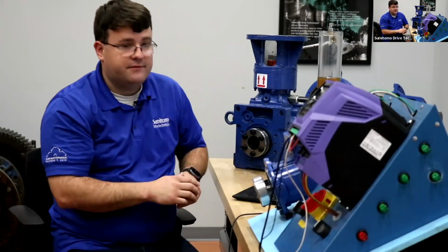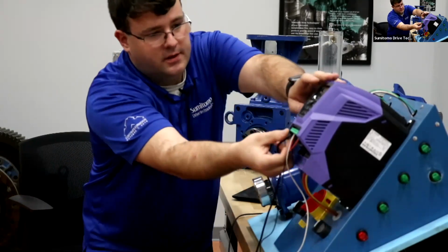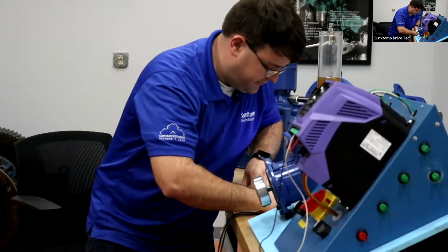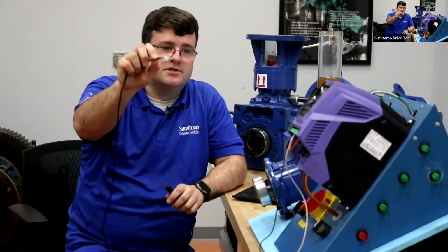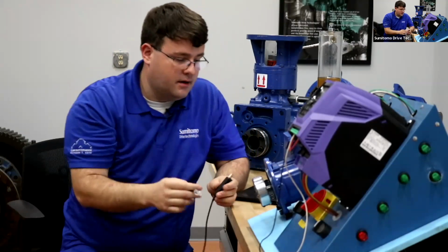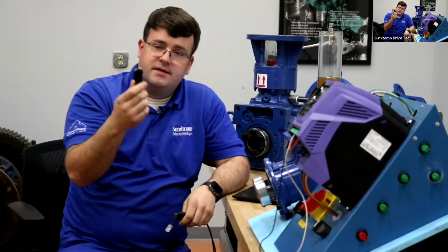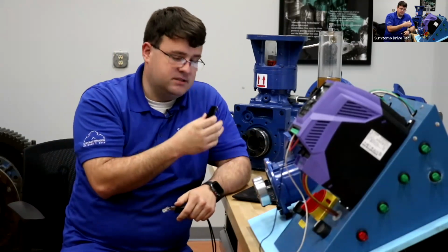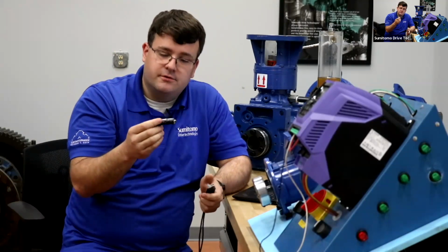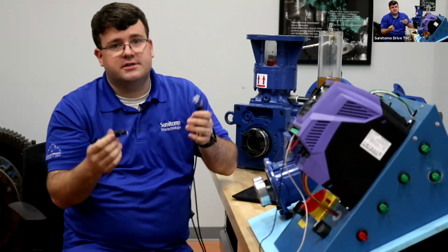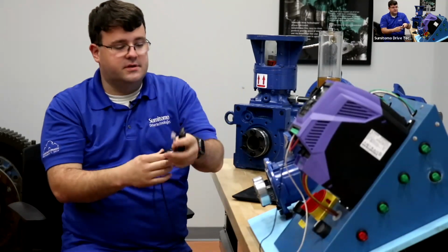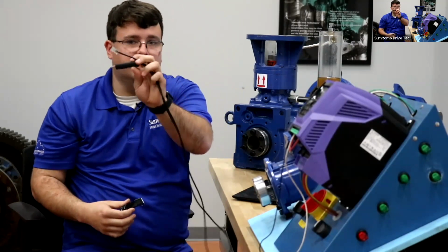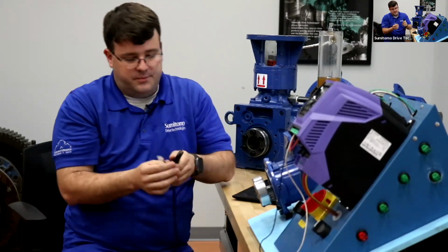Okay, perfect. Next question is, what communication interface are you connecting to the drive from the laptop? So from the drive to the laptop right now is wired. We have USB on the one end and then an RJ45 to the front there. You could also use the OptiStick, which is Bluetooth. If your laptop has Bluetooth, you could sync it up to the OptiStick and do everything I just did, wired or wireless. But for our purposes today, I was using a USB to RJ45, which we call the PC connection kit.